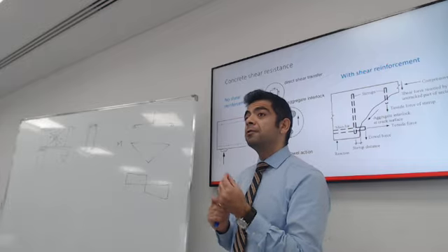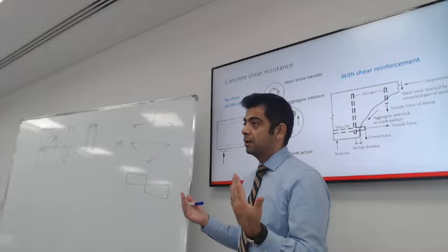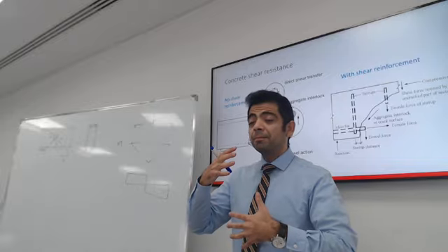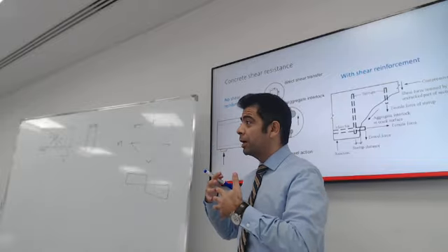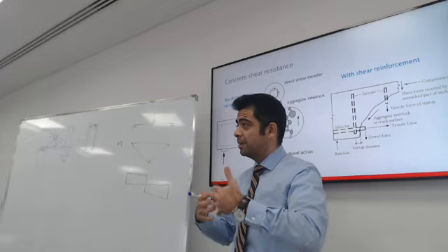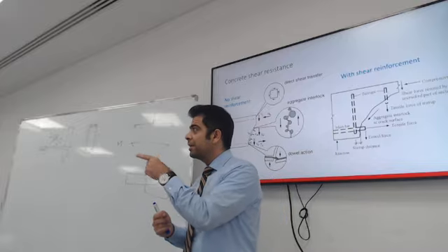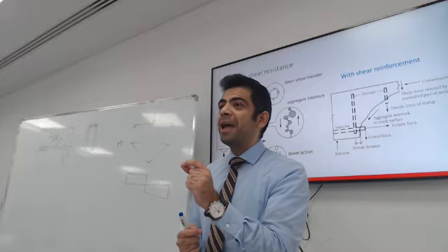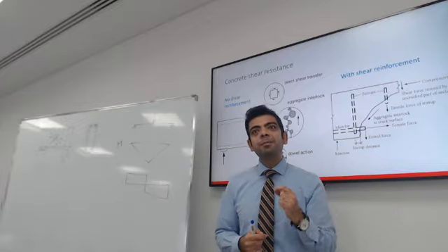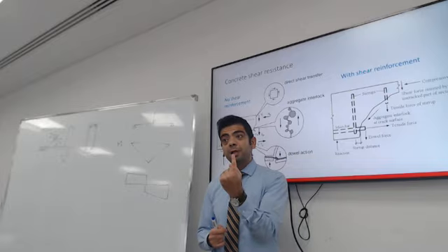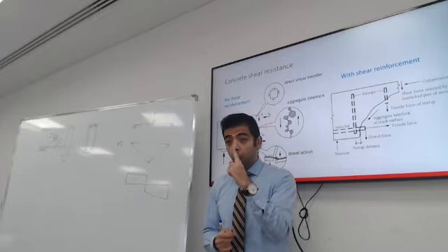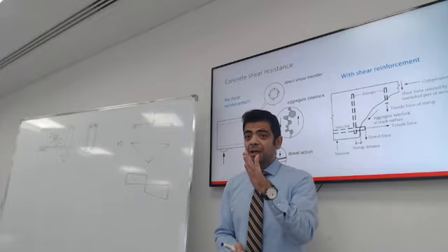Okay, what if the beam has no reinforcement? Does the concrete only, does it have some shear capacity? Yes, it does. And this is how we're going to design a beam in shear. We're going to first calculate how much concrete only, with no stirrups, can resist.